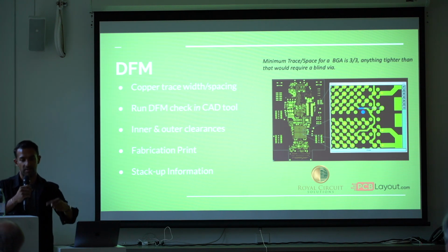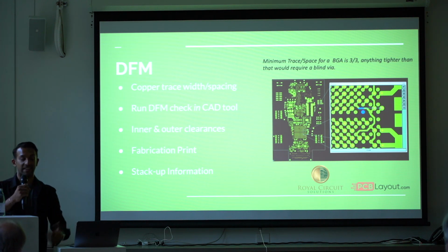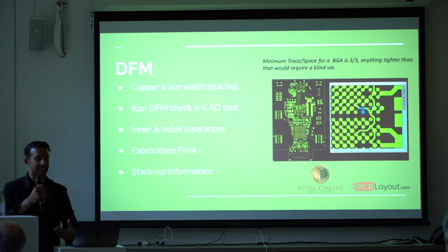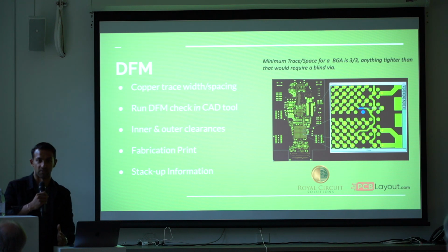I'll just drop it down between layers 2 and 3 and go around and make a really tiny 2 mil hole. And then it gets sent to us, and we have to give you guys somewhat of a reality check that if you want buried and blind vias, for example, at minimum, that's going to be about a 2 to 3 day turn. Even though I say, oh, everything's a 1 day turn, when you add a blind via and a